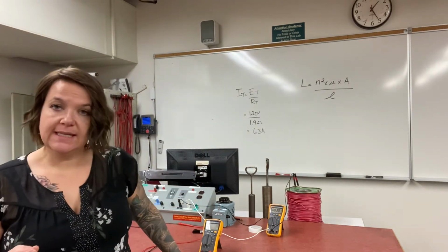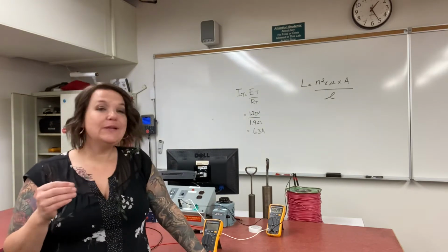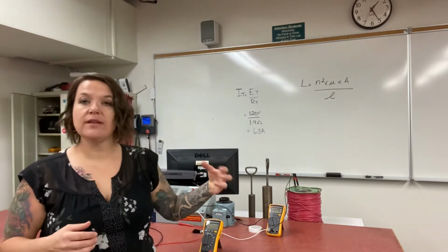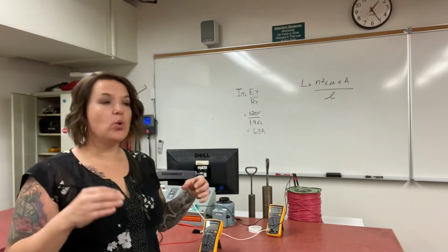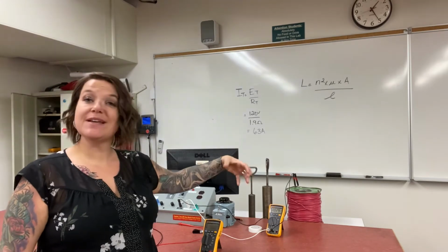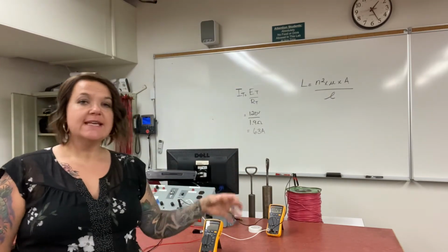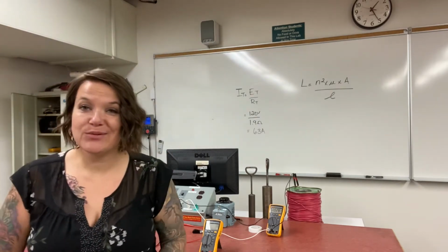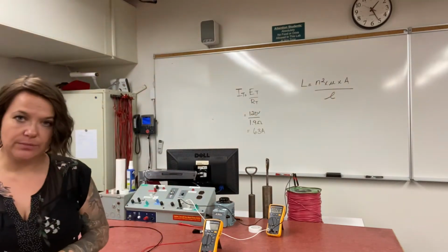The reason that I am only reading 8.2 amps is because this is a coil of wire and it's opposing that build of current simply by producing a counter EMF in our turns. That's opposing that rising current from our expected 63 amps to our 8.2, okay?